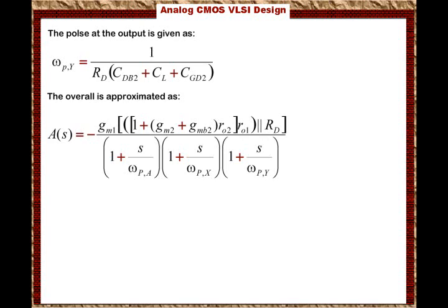function. Keep in mind that this is an approximation, and when you implement RD using another two cascoded transistors, this circuit becomes a little bit tedious to calculate using the S domain, and you have to have shortcut approximations. And one of the techniques to do is to look at R equivalent and C equivalent at each node, and this way you get the location of each pole at each node. And that's what we did here, and this technique is a valid approximation, especially in this particular circuit.